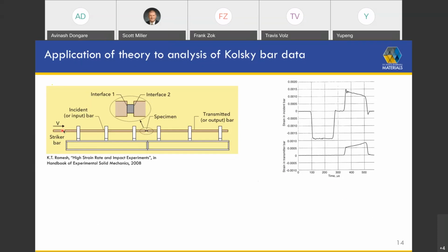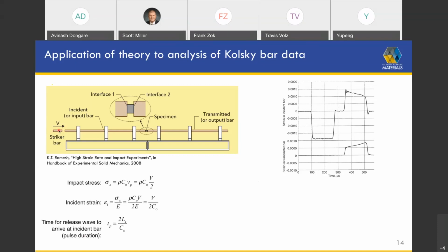that point, once the wavefront has reached this interface again, the stress in the bar and the strain in the bar will go to zero, because the reflected tensile wave on the back face perfectly cancels the incoming compressive wave. So the time associated with that is simply, it should be on the slide somewhere, twice the length of the bar divided by the wave speed within that bar.